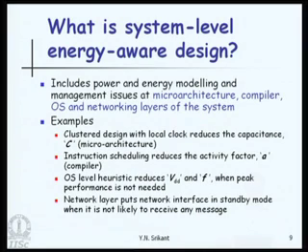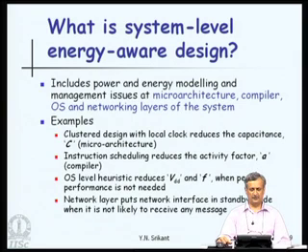Consider a clustered design with local clocks. In other words, there are clusters of function units, not just one function unit in the CPU, and instead of having a global clock for the several clusters, there would be a local clock for each cluster. This is a well known design strategy. It reduces the capacitance of the entire system. This is a microarchitecture level design consideration which can reduce power requirements, because once the capacitance decreases, the charge and discharge will be less, and power consumption will be reduced.